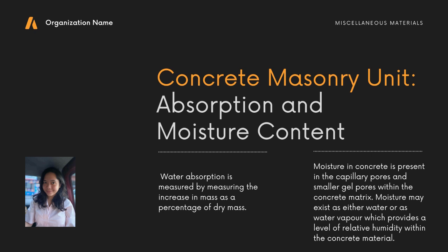In practice, aggregates in stockpiles, plants, and in the mixture are rarely, if ever, at these moisture conditions. The absorption of aggregate indicates the quantity of water which will be absorbed into the pore structure. Most commonly, aggregates will have a moisture content that is either below or above this absorption limit. When batching, it is of critical importance to account for this water.